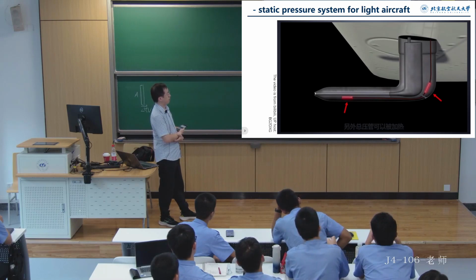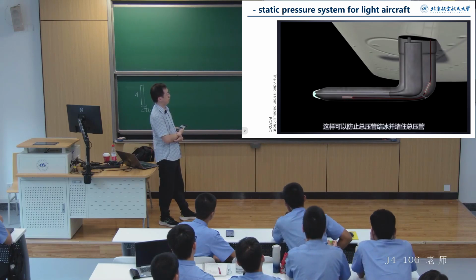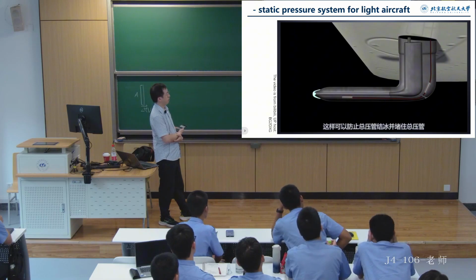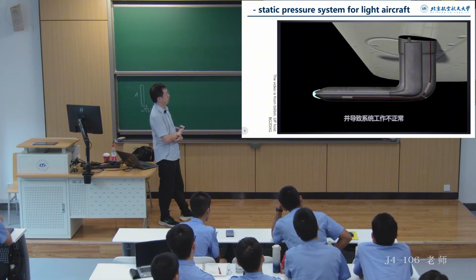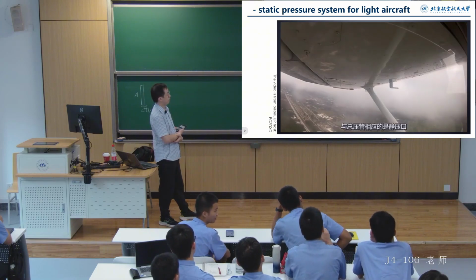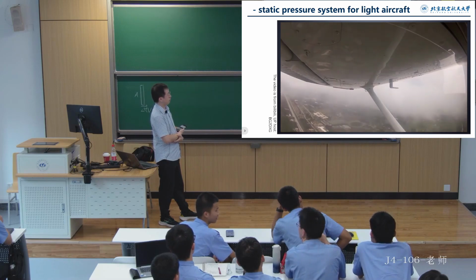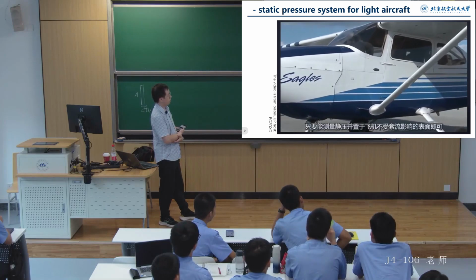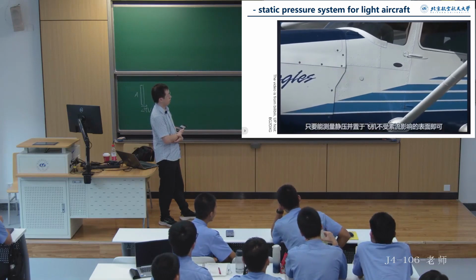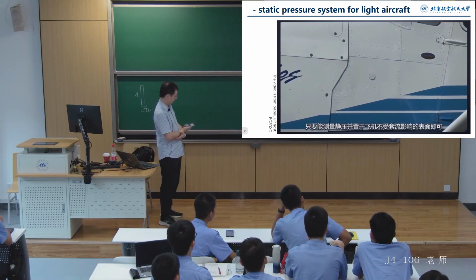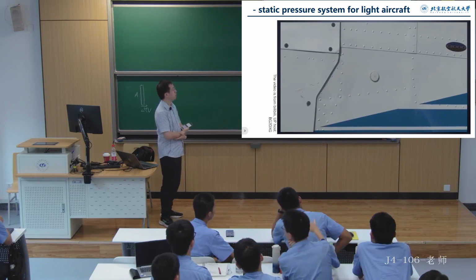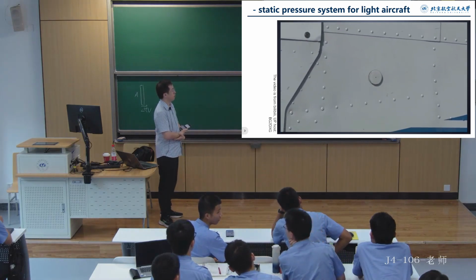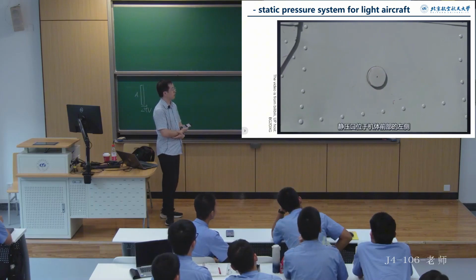Finally, the pitot tube can also be heated. This is used to prevent ice from forming on the tube, which could potentially block the hole and cause a malfunction. Functionally, the counterpart of the pitot tube is the static port. The location of this port will vary with different aircraft designs, and it should be positioned where it can measure the static pressure of the air, unaffected by the dynamic airflow around the airplane.